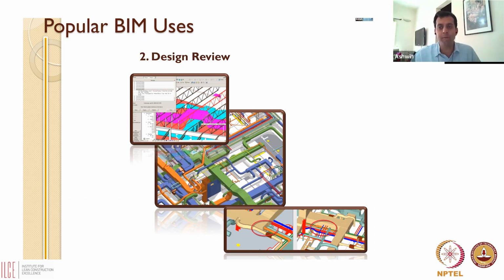What building information models can do is, because you have architectural information, structural information, and mechanical information coming together on the same platform, you can run a very simple query. You can ask the model, you have all of these pieces of information on your platform: are there any two elements, mechanical, electrical, civil, whatever, that share the same XYZ coordinates? And if so, that's a clash. Please list them out for me. So the computer very quickly looks at all the information you've put into the model and says, here are all the clashes that we've detected. Here are 27 different elements which are sharing the same XYZ coordinates.